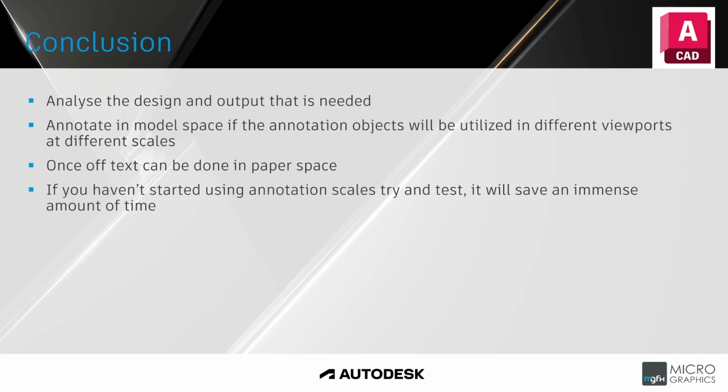Because once again, as I said, a small amount of text can be done in paper space. And if you haven't started using annotation scales yet, try testing it. There's nothing to lose. It's something that Autodesk has worked on, and I think it's been around since AutoCAD 2008. And you might find that you are able to increase your output, where as we all know, drawing is about 30% of your time on a project. A lot of time, I would say 60 to 70%, is detailing. There's a lot of detailing to be done.